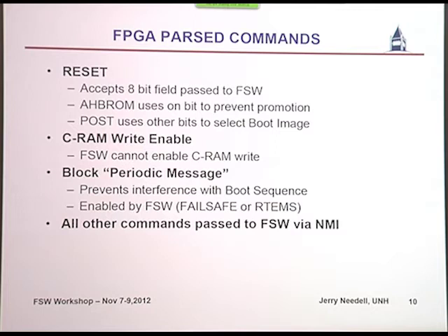Again, part of the FPGA design is to have a few commands that are parsed within the FPGA. Most commands are handled by the flight software, but a couple of them, the reset command is interpreted by the FPGA, resets the hardware, but it also passes an 8-bit field onto the flight software. A couple of those bits are used to either permit promotion to the power on self-test. Most of them are used in the higher level in the power on self-test to decide what boot image to use, and a lot of options. You got 8 bits to play with. You can make any decisions you want based on those.